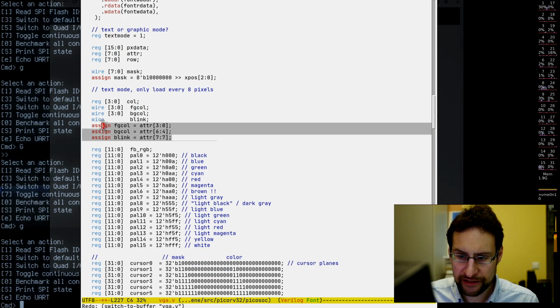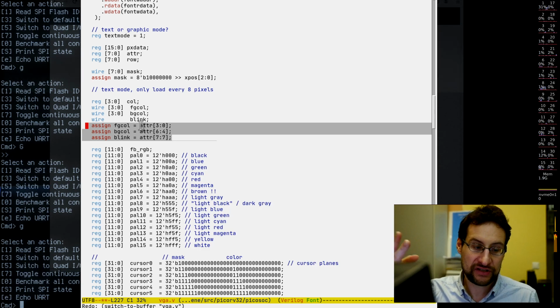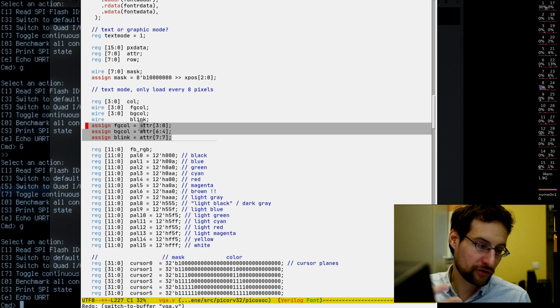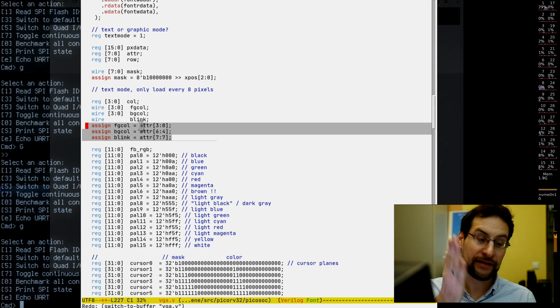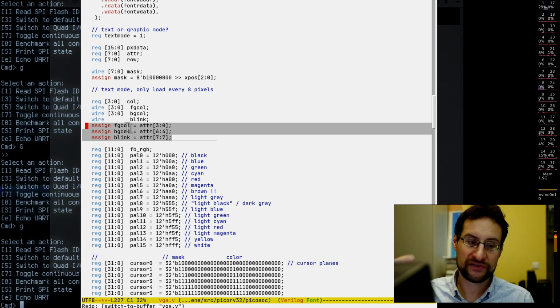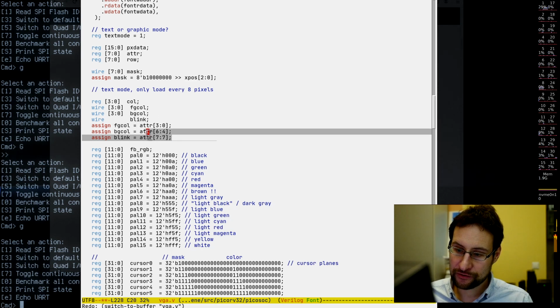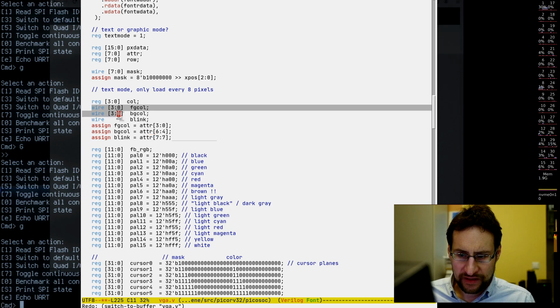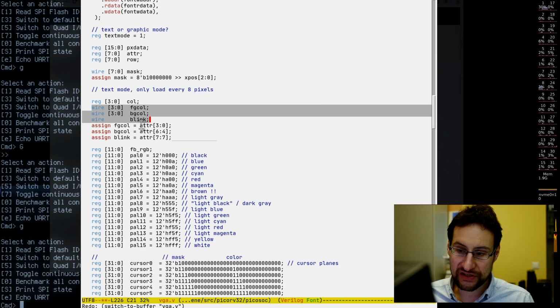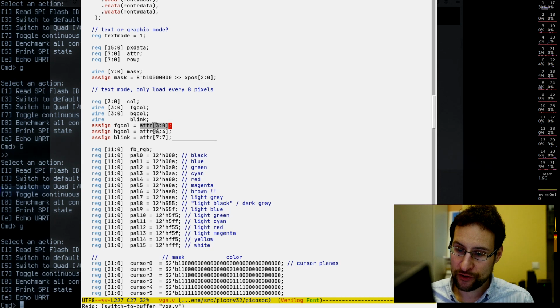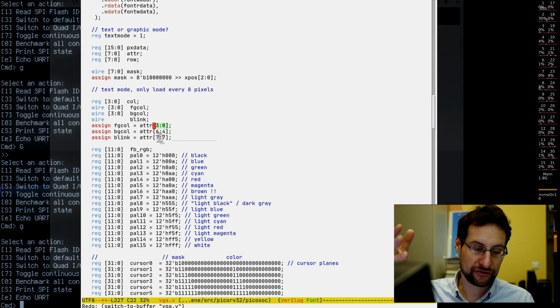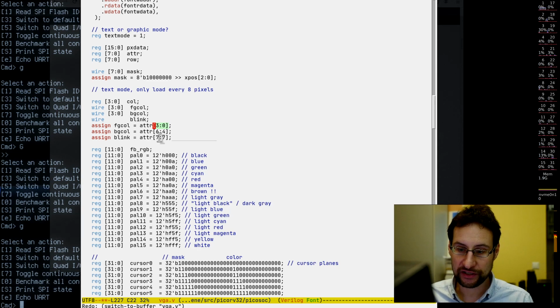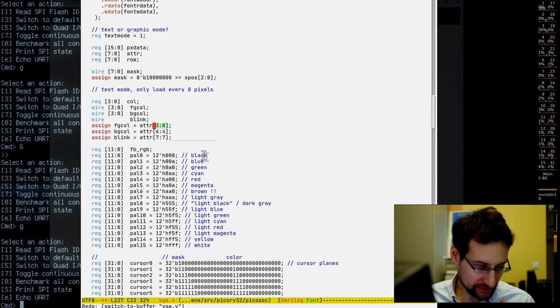Then, also hardwired foreground color. Initially, in my previous videos, I assigned this with non-blocking statements that had a 1 clock delay of propagating this from the flip-flop that latched this on the positive edge of the pixel clock to the end of this clock cycle. Learning this the hard way, optimizing the heck out of each clock delay, having this hardwired combinatorial logic means that this foreground color consists of wires that we directly assign to the bits of this text attribute, VGA compatible. The first 4 bits are the foreground color, then the next 3 bits background color, and then the blink attribute. So they are permanently hardwired to those register bits, and when those register flip-flops toggle, they change instantly, again with the propagation delay of the signal, but rather instantly.